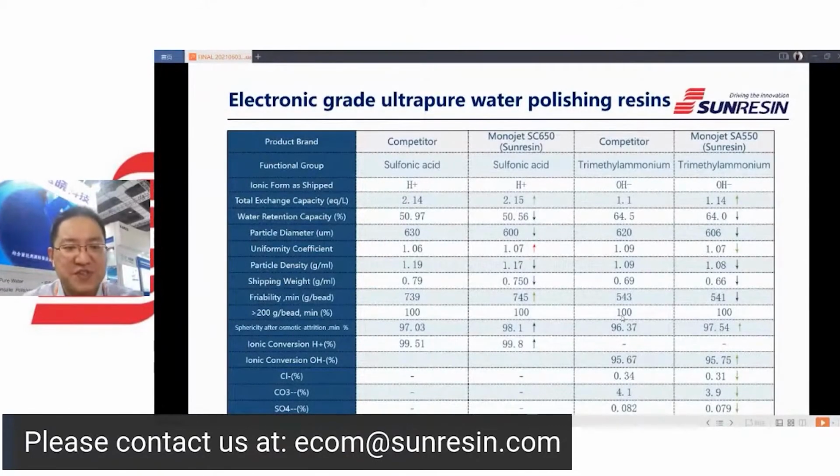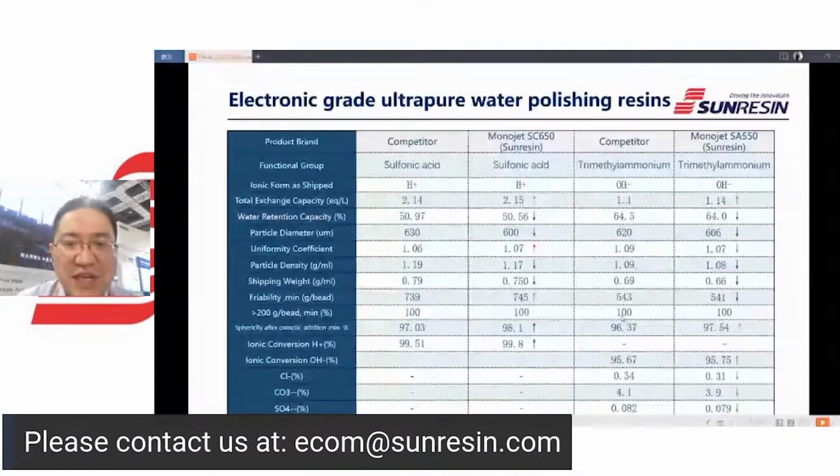The most commonly used resins in UPW are Monojet SC650U and SA550U. I have listed the detailed specs in the table. Comparing with the competitors, some of the specs, such as total exchange capacity, uniformity coefficient, and even friability, are almost the same, and our uniformity coefficient can be as low as 1.07.